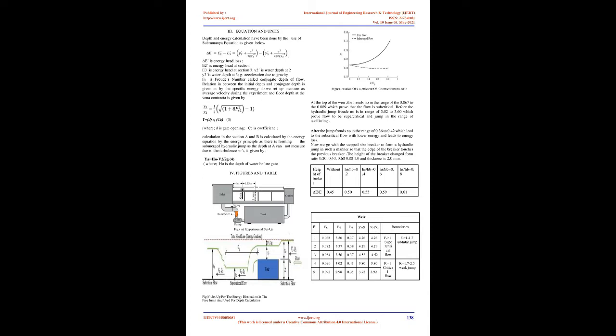Experimental calculations have been done on the assumption of energy loss in friction, as the length of the hydraulic jump is very small, which is justified. Experiments have been done by measuring the depth using a point gauge, averaging 3 depths in the middle of the flume. For the theoretical calculation, the equations of Subramanya have been used, e.g. for depth calculation and energy loss.